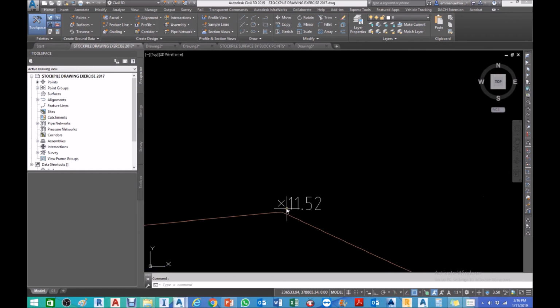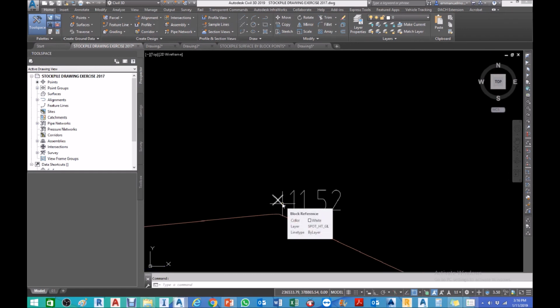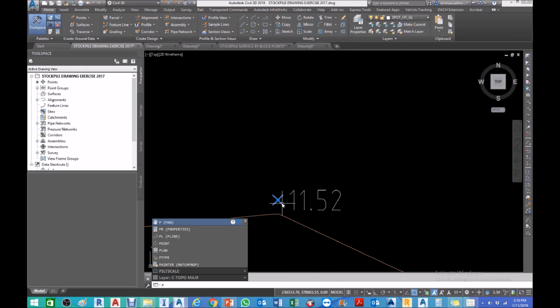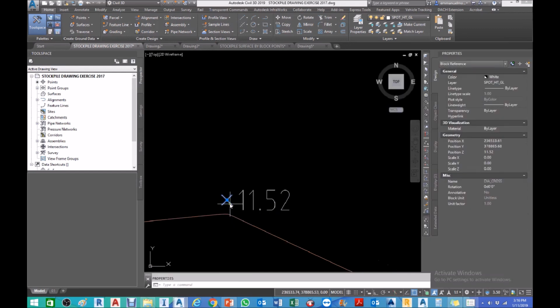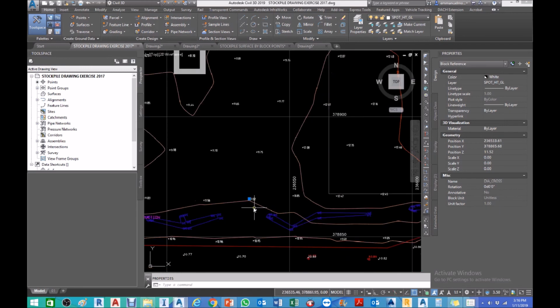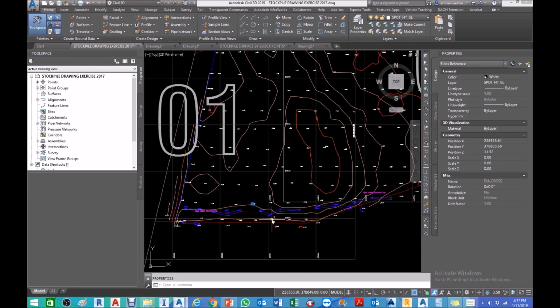But when I inspected that one, if I'm doing it like this only, some points do not have elevation. Now you need to verify the cut and fill. The problem also is that the contractor did not make an inspection on the first part of the project. They did not make the topo again for the existing roads.